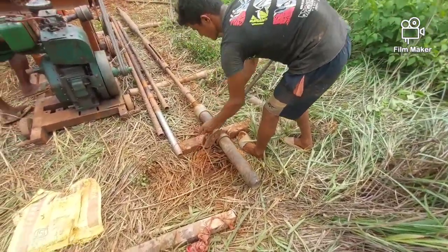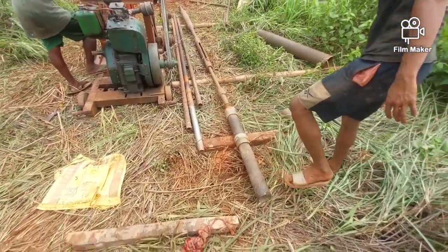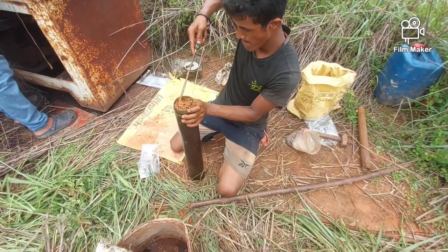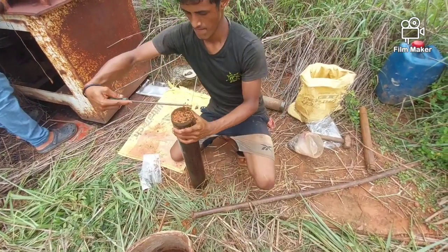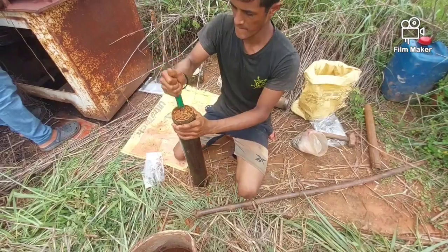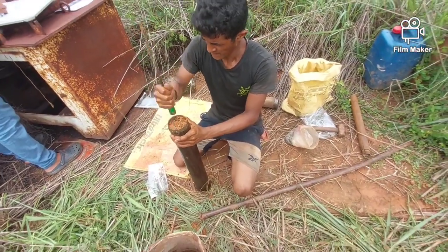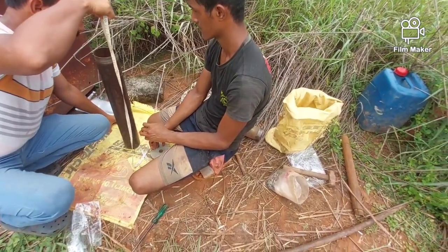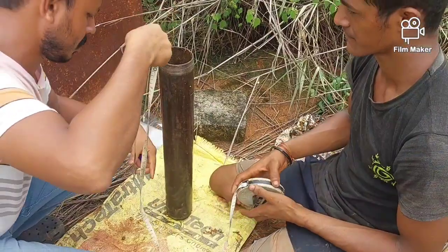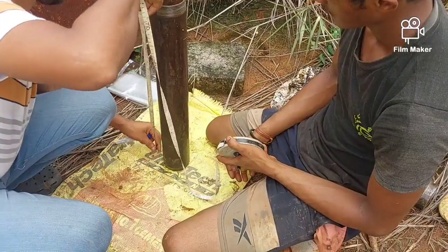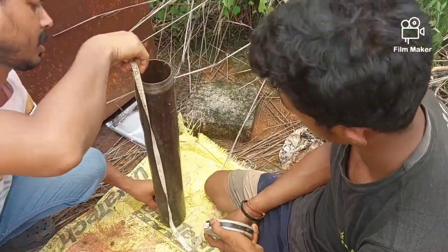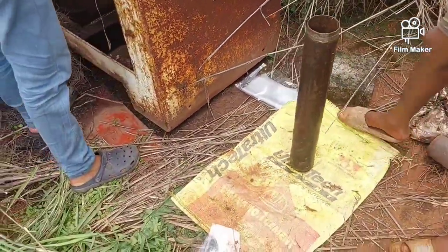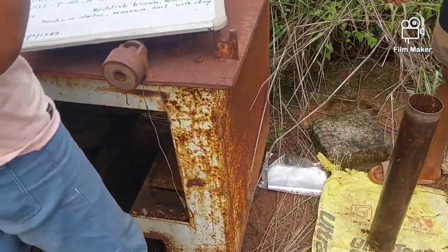Another sample barrel is removed from the borehole, and the sample is taken. So we will see how the sample is collected from the barrel. Here they first remove the top and bottom of the barrel, and then it is compacted and they measure the depth of the recovered sample against the full length of the barrel, and how much length of sample there is.